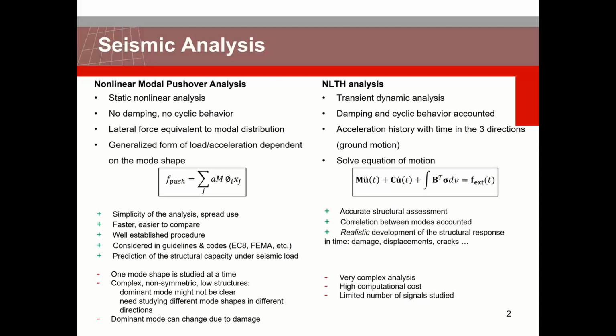To start with, the pushover analysis is a static nonlinear analysis in which damping and cyclic behavior are not considered, and a lateral force equivalent to the modal distribution is applied to the structure. So there's a generalized form of the load that is dependent on the mode shape, and this would be very complex and time consuming to do by hand, but in Diana we have this pushover force, a lateral force that is equivalent to a given modal distribution. This is computed automatically in Diana.